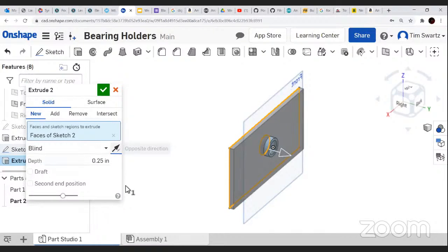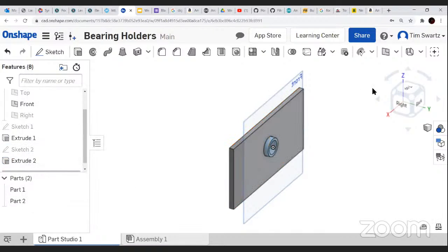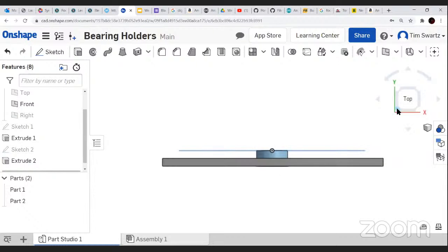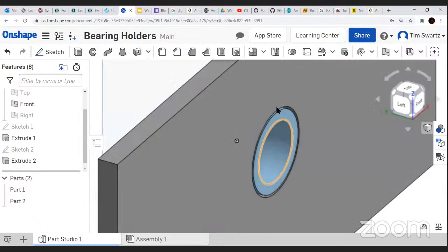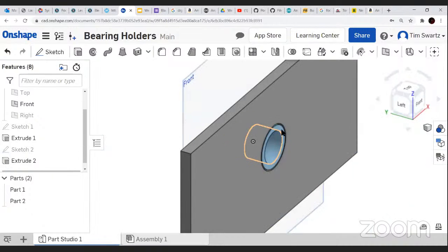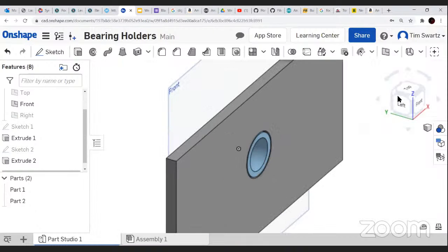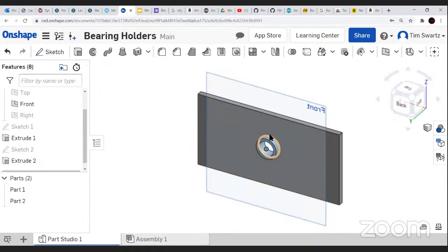We're going to reverse that. So you can see here, this is probably what it's going to look like. The hole here is going to be used for locating it rather accurately, but it's going to have a little bit of slop, you can see right there. And then we're going to make some 3D printed parts that retain the bearing on the backside and then bolt in to the face here.